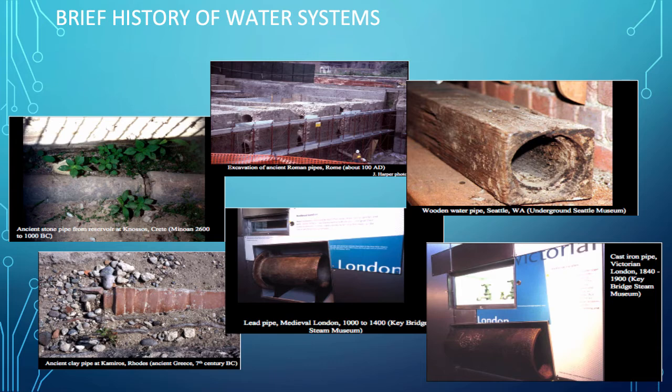Nowadays, it's a pretty specialized pipe, but it has some advantages with certain kinds of corrosive waters. It's a really good wastewater pipe. It takes a fairly high skill level to install the pipe, and it needs to be in very stable soil so it doesn't break. So clay pipe is still in use today, and probably modern clay pipe, the manufacture is not a whole lot different than the ancient clay pipe.